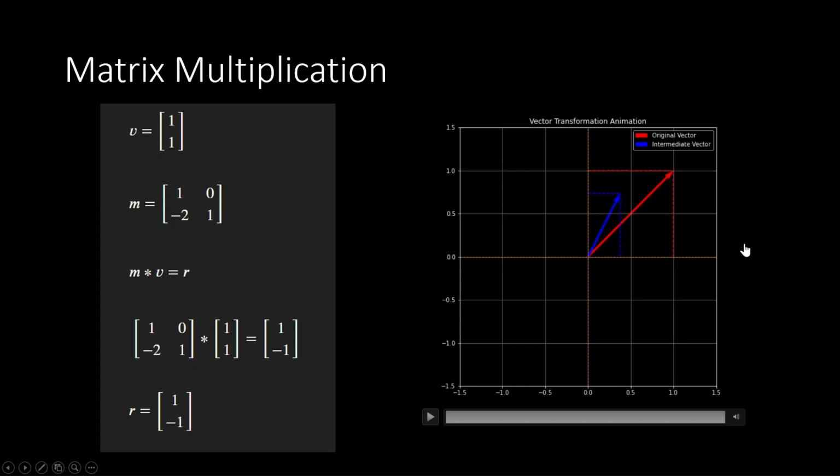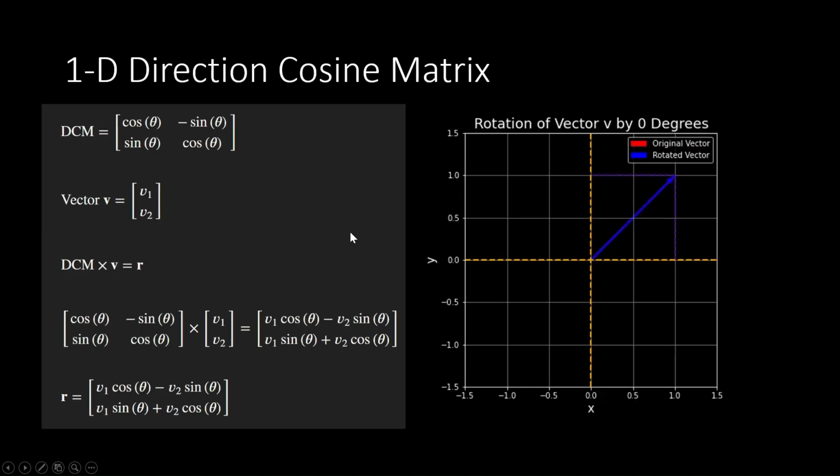What we're trying to show here is a special form of matrices which causes perfect rotation of vectors, and they are called direction cosine matrices, or direction cosine matrix. So essentially this is how it looks. We have some angle of rotation, say coming from a roll sensor or pitch or yaw, any of these, and we read that sensor and construct a matrix like this: cos of angle, minus sine of angle, sine of angle, and cos of angle. This might be roll or pitch or whatever.